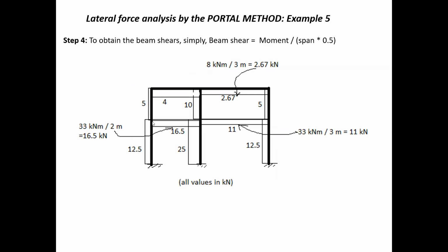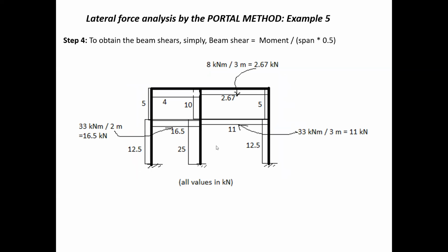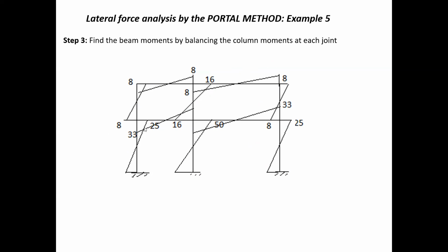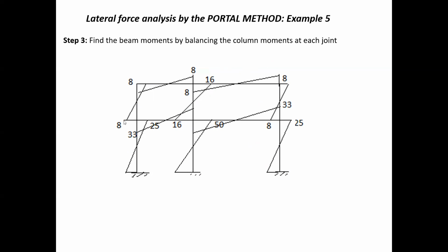It's very, very simple to find the shear force. Okay, so you just get twice the moment divided by the length. Now look at this one, twice the moment, 50 plus 50, or 2 times 50 divided by the length is 25, obviously. So you got shear force of 25. And this end one here, well, we've already done it for 25, so it's the same. Now let's look at this one here. You've got 8 and 8.